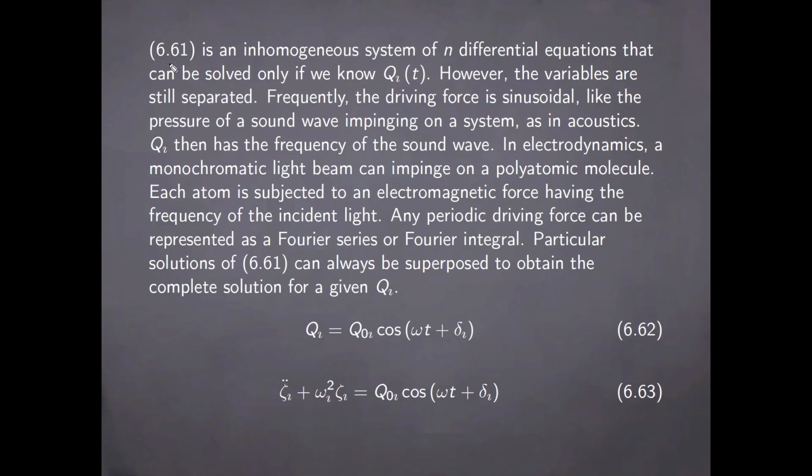So what we have obtained is an inhomogeneous system of n differential equations that can be solved only if we know the dependence on time of these generalized forces corresponding to each of the normal coordinates. However, the variables are still separated, and quite frequently the driving force is sinusoidal, as is the case, for example, of the pressure generated by a sound wave impinging on a system in acoustics, and then the generalized force has the frequency of the sound wave.